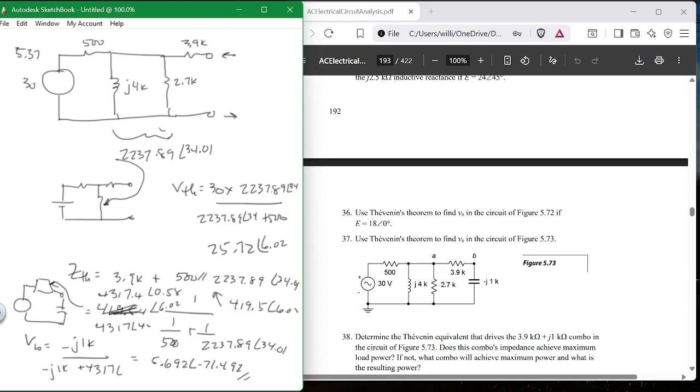And it does explain things like when you walk into a factory, why they have to put capacitors in to bring down the current, to keep the energy in, to minimize the energy usage in your factory. You have to complement the inductors, which are motors, with capacitors. So all the time, you're hanging capacitors on a motor starter circuit. Why? Because it brings your current down.